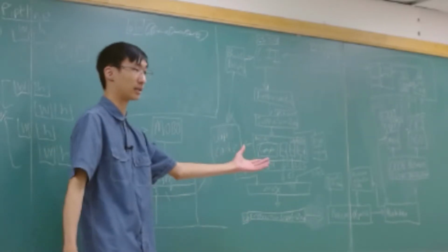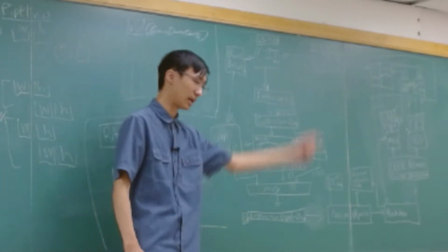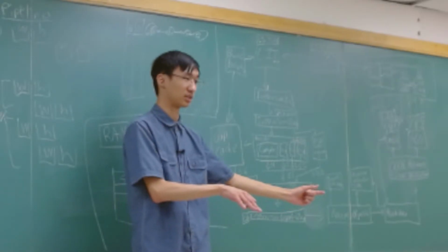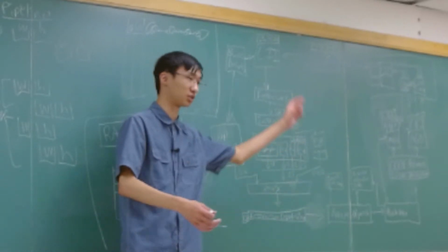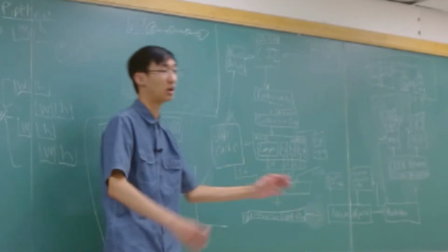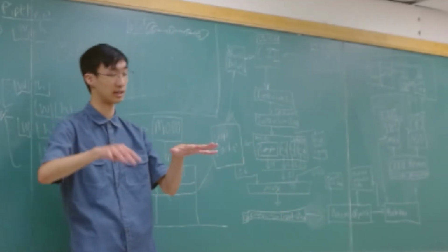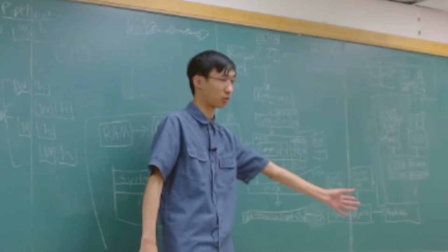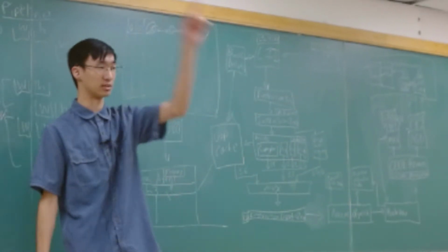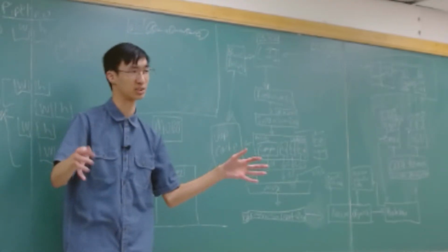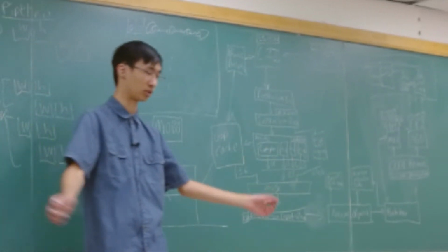And then the other thing is that you could have something like an agree predictor, which says, hey, that prediction is not generally accepted, so don't use that one, and just use this global prediction method instead. Or if you don't get any hits in your address table for that history set, then you will use some other prediction method like the global prediction, and then you'll update the system. And the system really acts kind of similarly to the perceptron, where you'll also update weights. You'll have weights for each of those.